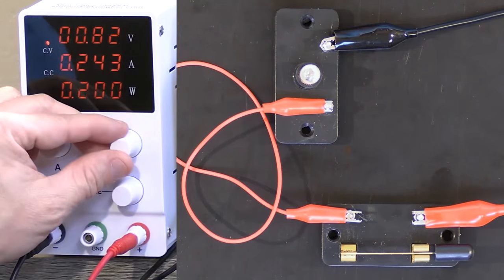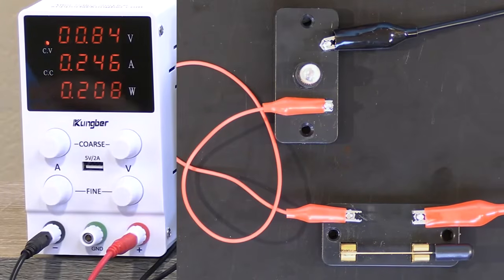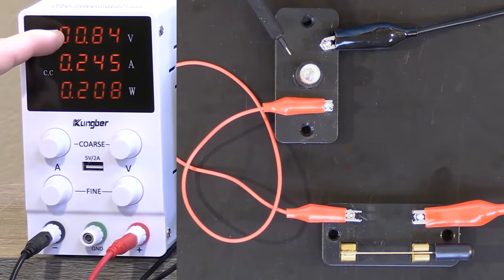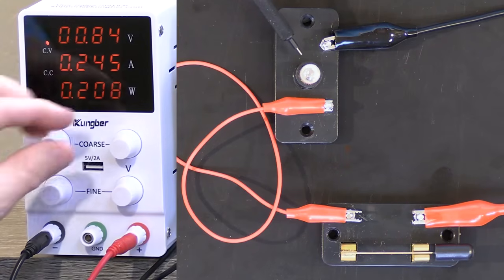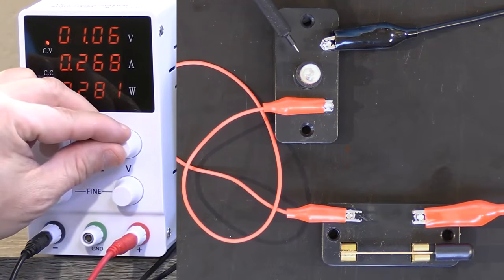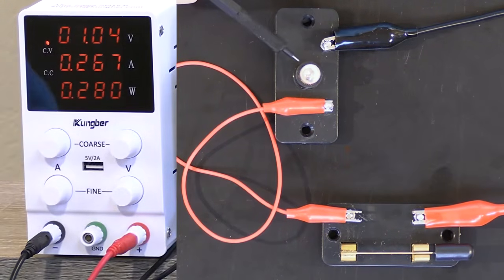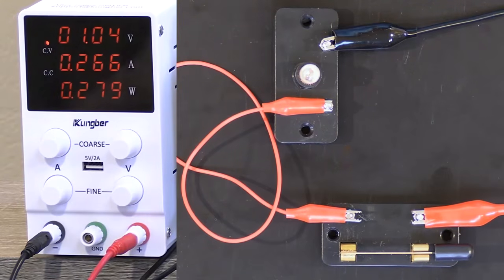All right, let's go up to 0.84. Right, I'm not seeing much. I think I'm seeing a very, very small illumination down here. So small you may not be able to see it on the camera, but notice when I increase the voltage, the current also increased. When I increased the voltage to a volt, the current increased, and now I can see a little bit of light because now I have enough current for the friction, the resistance in that light bulb, to heat up the filament, and then it makes light, right?